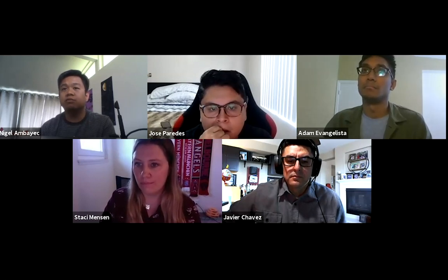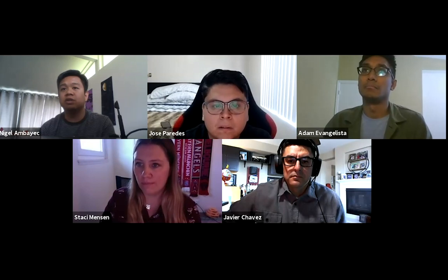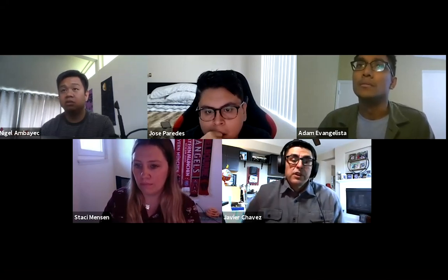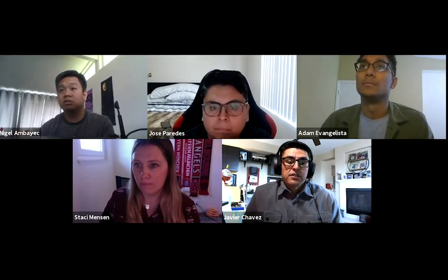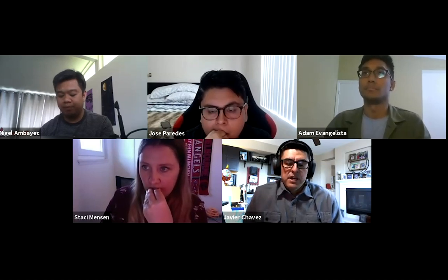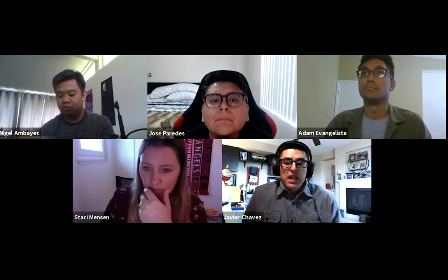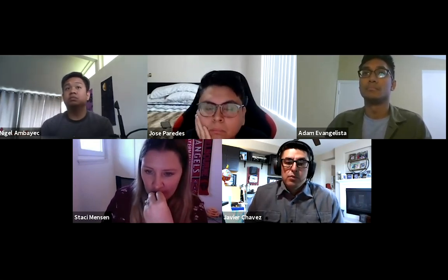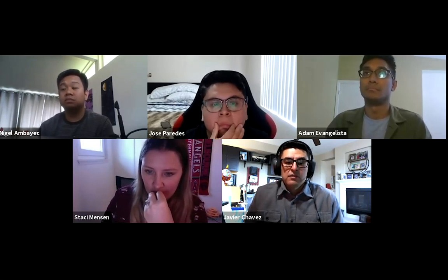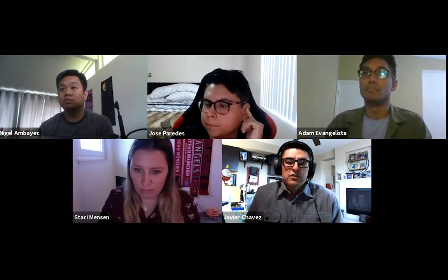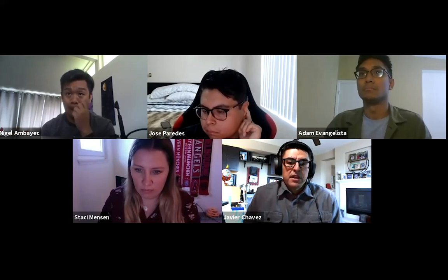All right, next question. For remote work, is there an advantage of having the content center stored in the vault? So really the only reason that would be necessary is if the content center is customized. And we're talking about the libraries, right? If it's customized, then it makes sense to put it on the vault. If it's not customized, it makes sense to use the desktop content, and that points to a location locally on your machine that's available 24/7 without a vault login. So I'm pretty sure that's what you're asking about, and that would be the answer.